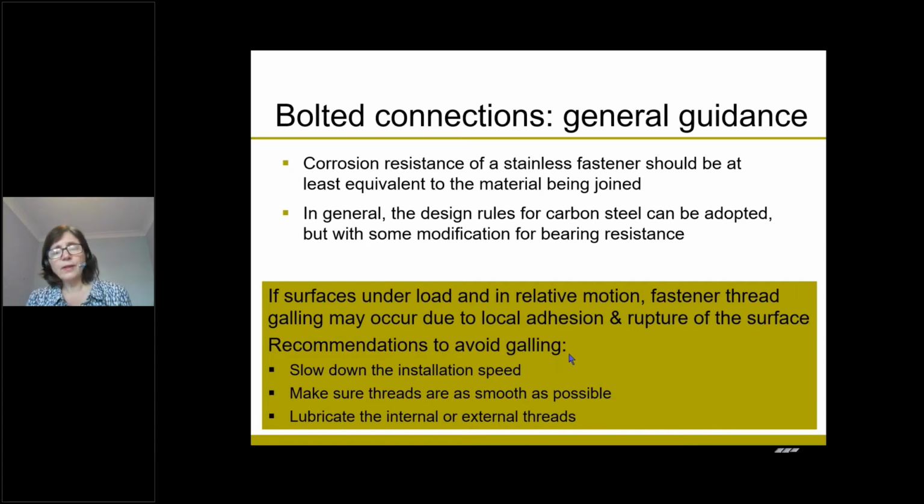Just a couple of things I wanted to flag up. One is that you do have to make sure that the corrosion resistance of the fastener you choose should be at least equivalent to the corrosion resistance of the material being joined. That's important to ensure a long-lasting, durable connection.